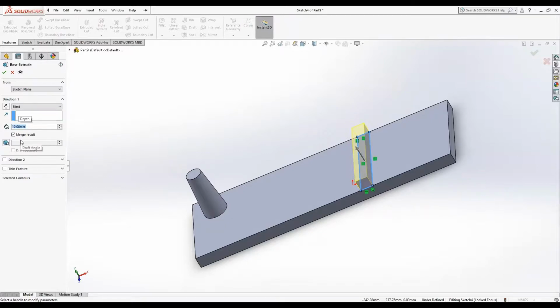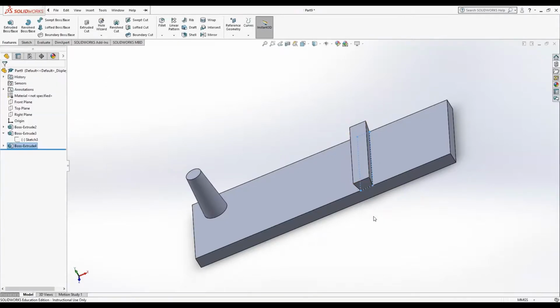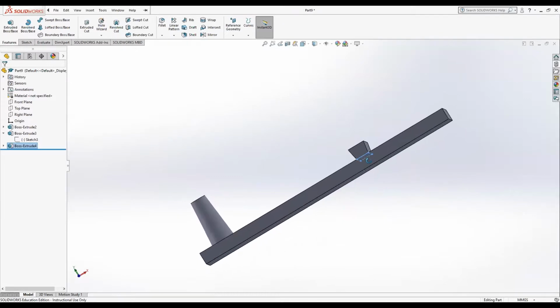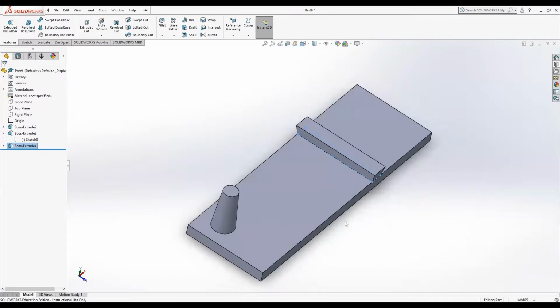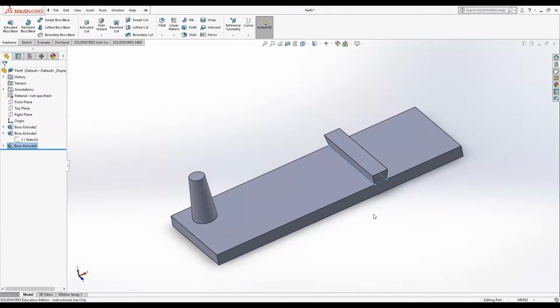And then we can do, remember how we did our draft? Well, this is a draft for still 1 degree. Let's make this a 10 degree, so it's pretty obvious. See, you see it taper in like that. Once again, that's just a taper point, but you can draft outwards. We draft outwards, and we'll give it a checkpoint here. And you see there we've created a dovetail key off of that point. So when you're merging parts together or things like that, occasionally dovetails are a good way to join pieces together or to create slides. And this is how you would draw those dovetails.